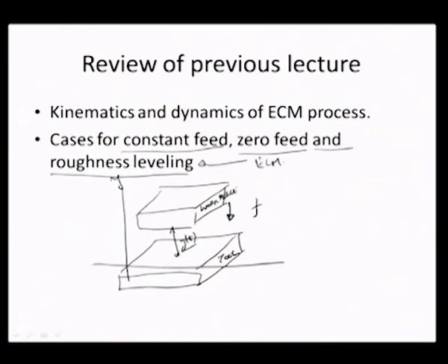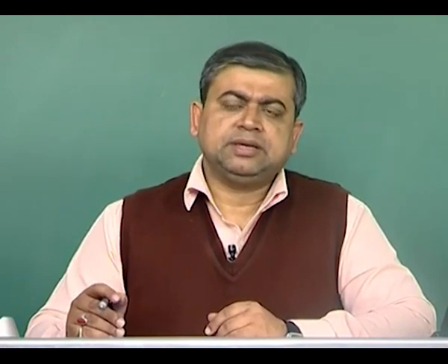ECM process. Today we would look into a slightly different aspect of the ECM, which is very critical for designing particularly electrochemical machining systems for microsystems design and fabrication. And so that is related to the electrolyte circulation or the electrolyte flow. So basically there is a possibility that the electrolyte in an ECM process moves through a very small gap because the equilibrium gap is a few hundred microns, and because of this continuous movement and a high value of current density, there is always a possibility of the electrolyte liquid hitting the boiling point sometimes.